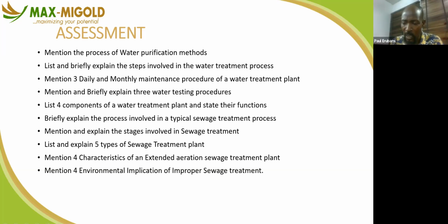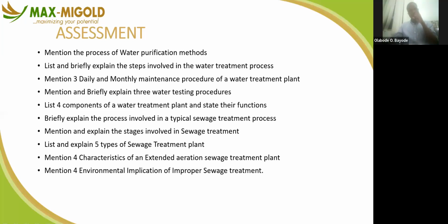So if you want to do this, that means you have to shut down the entire sewage drainage for at least 24 to 48 hours. There won't be a single drop of water coming in. Then you have to excavate the entire manhole and redo a very fresh one. The interior of that manhole will be finished with what we call water cement, and you have to leave it for at least 24 to 48 hours for curing. Once you apply that, you will resolve the problem. But if you are just applying cement and 2 hours later somebody is washing dishes, somebody has started taking his bath, it will wash off the cement. It won't cure. I agree, sir. Thank you, sir.